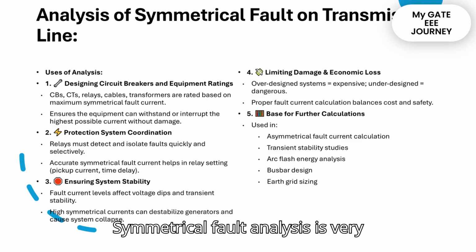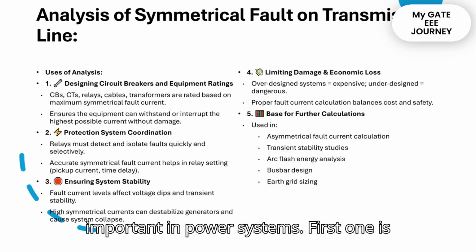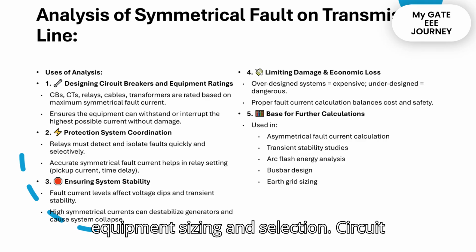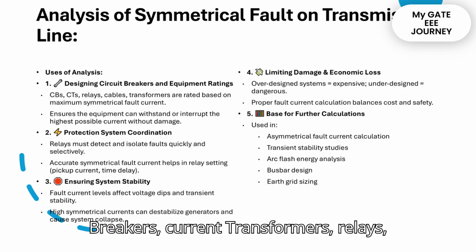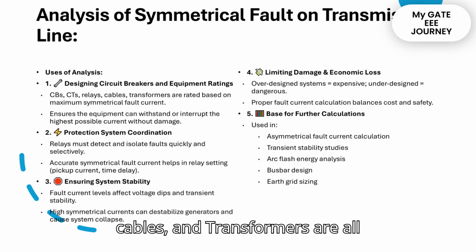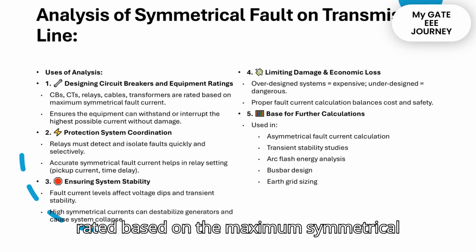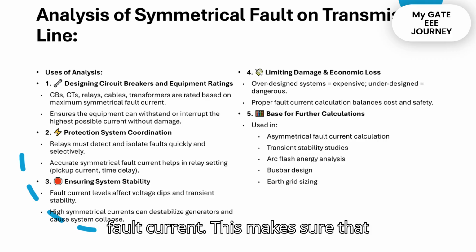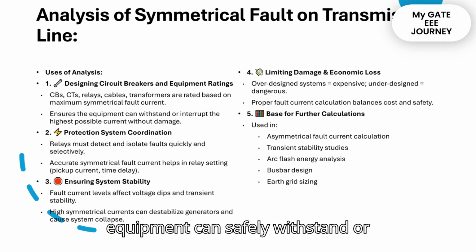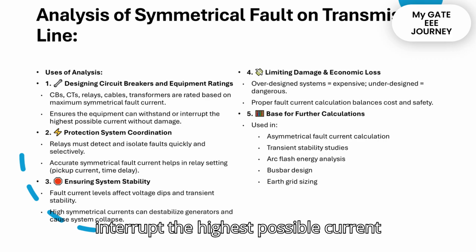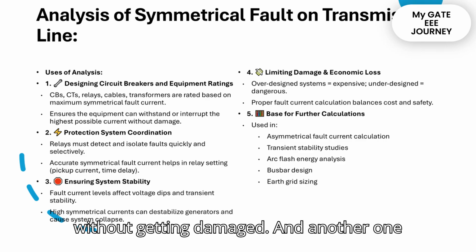Symmetrical fault analysis is very important in power systems. First one is equipment sizing and selection. Circuit breakers, current transformers, relays, cables and transformers are all rated based on the maximum symmetrical fault current. This makes sure that equipment can safely withstand or interrupt the highest possible current without getting damaged.